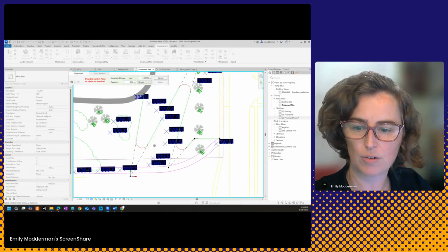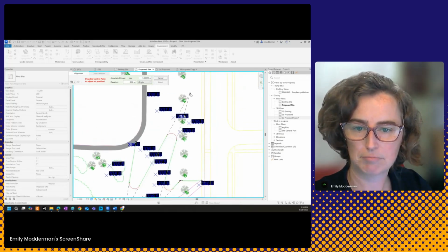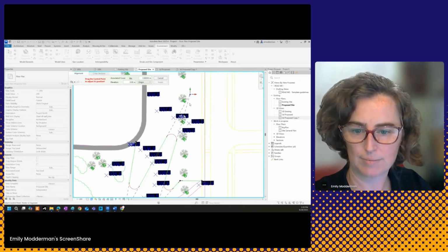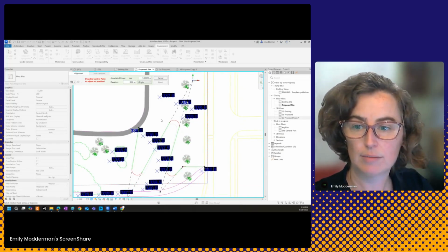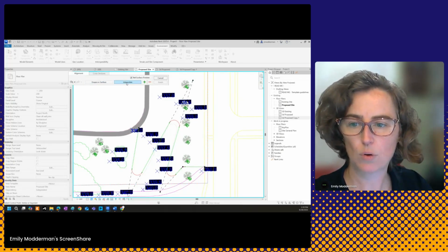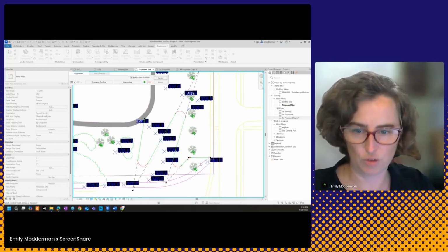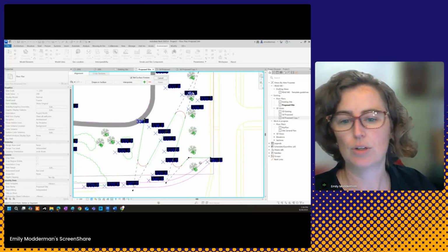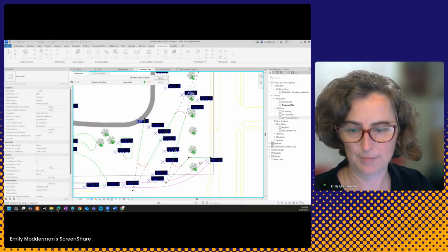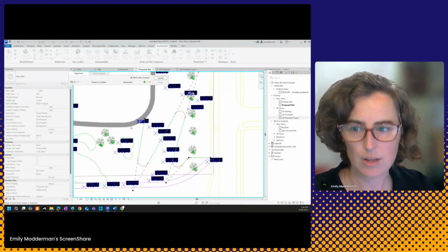All right, so I'm going to adjust this, and there we go. So roughly when I'm happy with this, I will hit escape again. And then we have drape or interpolate. So drape would mean I have an acceptable slope between these 2 points, and I want to use as much of the existing landscape as possible to form this pathway. Okay, this is great when somebody else is doing a lot of that civil work for you.